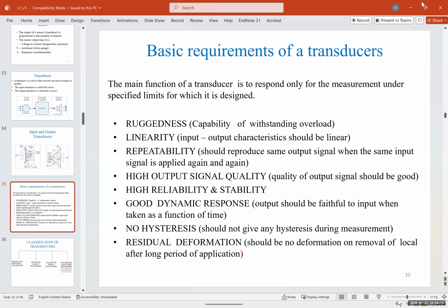One example that I could give: if you put a steel nail in a magnetic field and keep it there for a few hours, that nail would become magnetic. Imagine if that is part of a sensor. Now the sensor has shifted, the measurements have shifted. So we shouldn't have that hysteresis effect, meaning it shouldn't deform or keep the previous measurements.